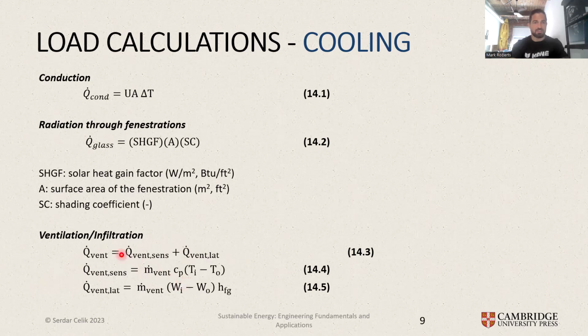And again, ventilation can involve sensible and latent heat. The sensible heat is going to be the amount of flow of the air that's being vented or flowing in times the temperature difference. So this is based on the rate of flow of mass into a building. And then the latent heat from ventilation or infiltration can be related to a phase change. This could be related to maybe water evaporating, which requires absorbing heat, or water condensing.